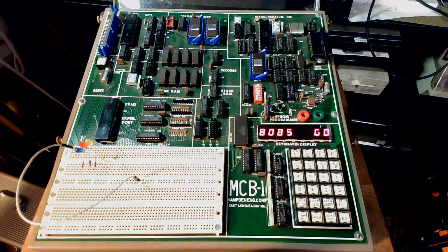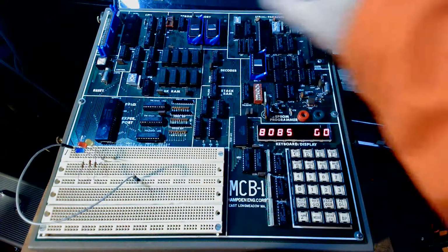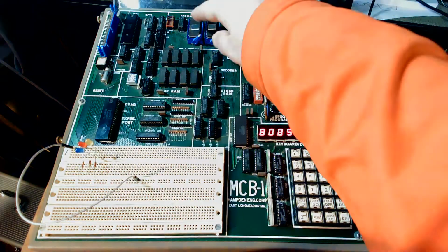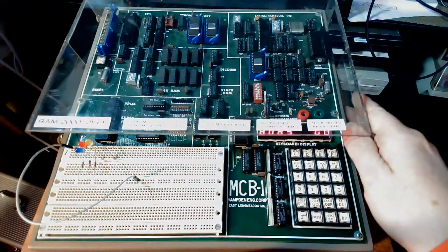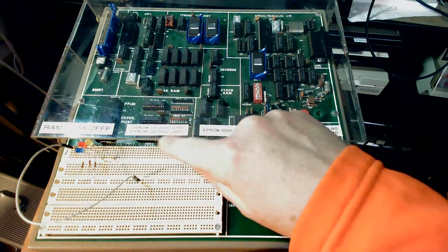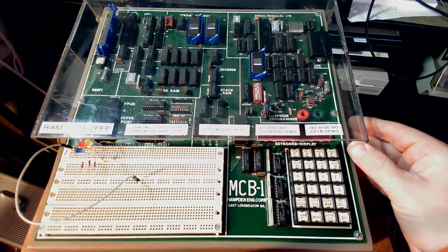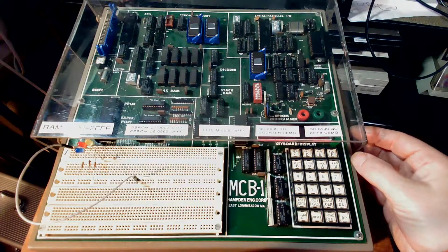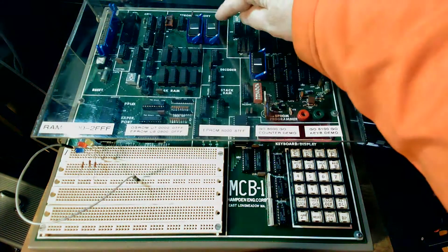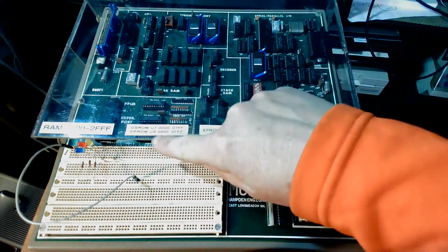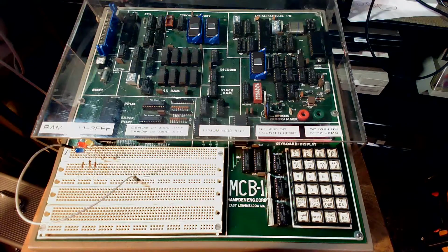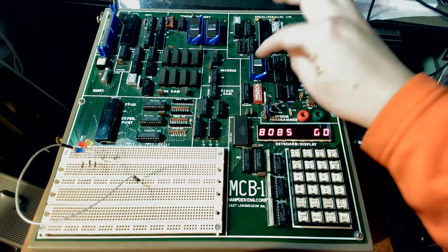So all of those are 2716As, and I burned them on the PC with the Mini Pro TL EEPROM burner. So you can also basically change the address ranges into which these ROMs are mapped. For example, the OS ROM, and I made stickers here, goes from 0 to 07FF, right? So those are 2 kilobyte ROMs, 2716s, right? And then this optional user ROM goes from 0800 to 0FFF, and then the EEPROM goes from 8000 to 87FF.